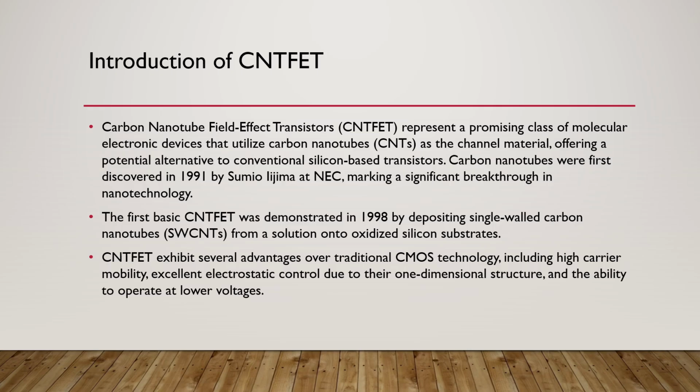The first basic CNT FET was demonstrated in 1998 by depositing a single-wall carbon nanotube (SW-CNT) from a solution onto a silicon substrate. CNT FETs exhibit several advantages over traditional CMOS technology, including a high carrier mobility, excellent electrostatic control due to their one-dimensional structure, and the ability to operate at low voltage.